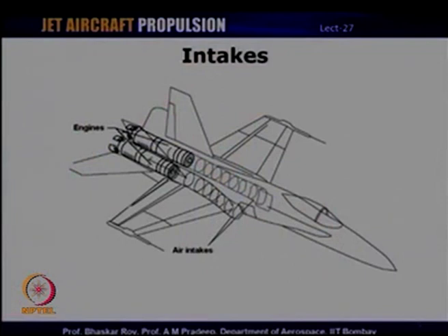but many of the aircraft usually operate with fixed air intake geometry. But in military aircraft, on the other hand, a supersonic intake for example, would usually have a variable geometry intake to ensure that this intake can operate safely under subsonic conditions as well as under supersonic conditions, and so that will necessitate that the intake has certain variable geometric features incorporated in its design. So, I will show you some typical examples of air intake geometries which have been used and which are currently used in some of the civil as well as military aircraft engines.